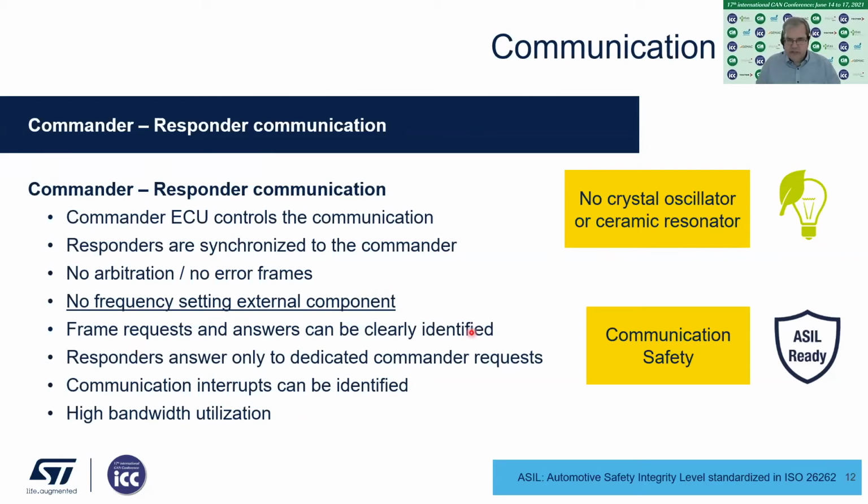Frame requests and answers can be clearly identified, so this adds a lot to the communication safety. The responders answer only to dedicated commander requests, and communication interrupts can be clearly identified because the commander knows from which responder to expect an answer. And if we have a dedicated communication scheme without arbitration, then the responder also knows within what time frame it expects a certain communication from the commander. So we can implement a watchdog. And with all of that, we also get a high bandwidth utilization.